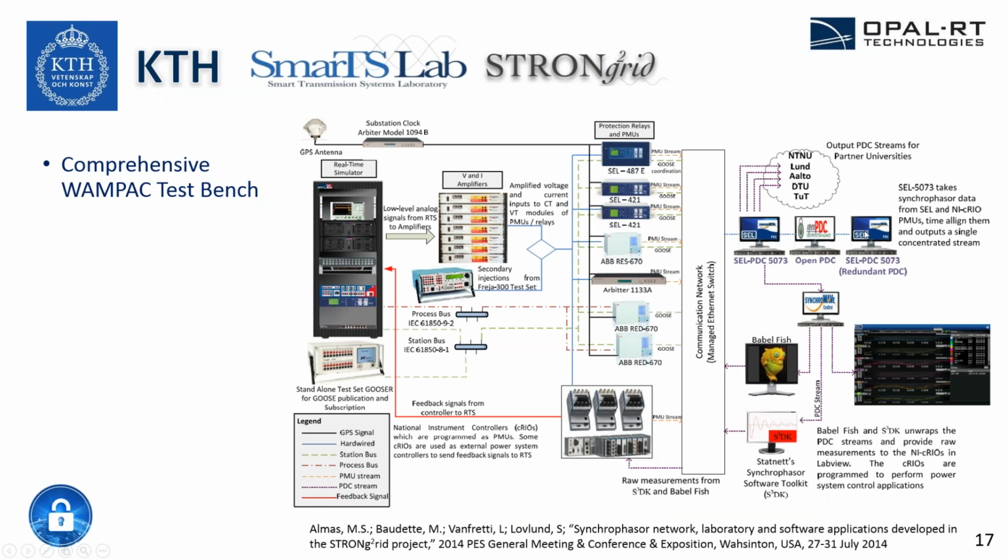And the first users that come to mind are KTH. So KTH have a very comprehensive wide area monitoring, protection, and control test bench. They have a real-time simulator that's connected to real hardware in the form of PMUs and protection relays. They have amplifiers that create a high-power interface between the two. They have controllers in the loop that they've custom designed using basic National Instruments modules.